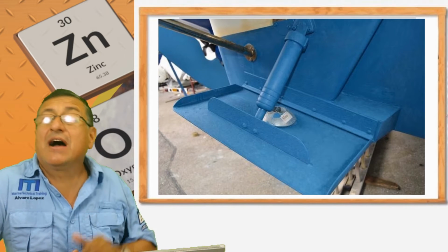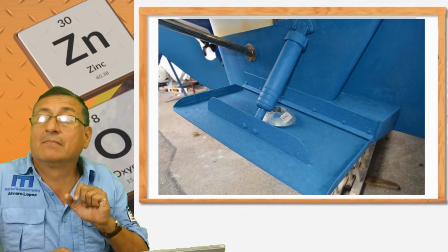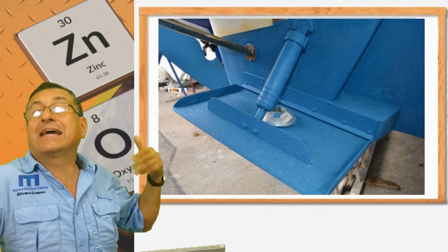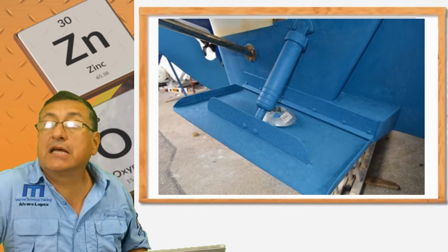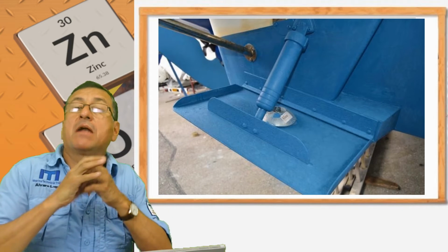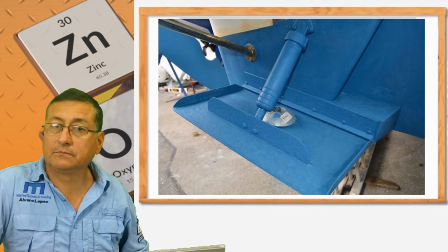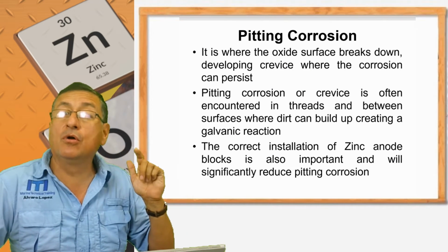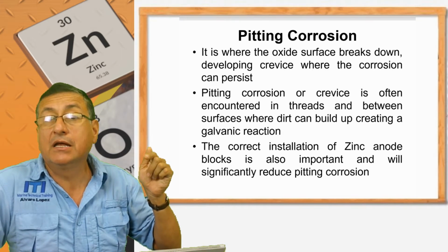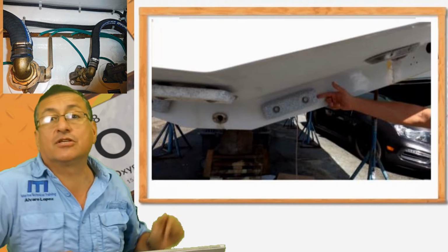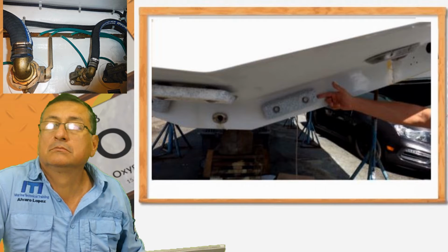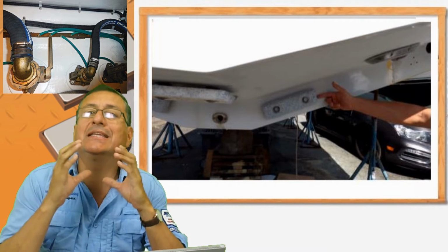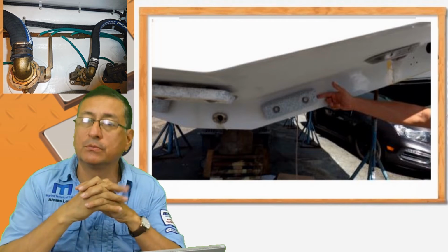You have specialized electrodes, sacrificial anodes for the external elements in permanent contact with the water. For the elements located inside of the boat connected to the bonding, I have the zincs on the transom. Now it's clear? This is the process, this is the procedure.